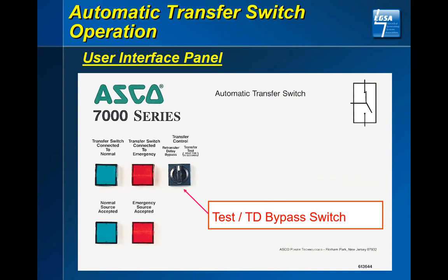If you turn that, and in this case I think it holds for a few seconds or such. Yeah, hold it up for 15 seconds. It will not only start the generator set, it will transfer, and it'll put that into the minimum run timer, and then it'll transfer back to your normal source. You can notice to the left side, there is a bypass. Okay, I'm tired, I proved what I needed to do. You throw it to the left side, it'll transfer and go back to the normal source. So I hope several of these have made sense.